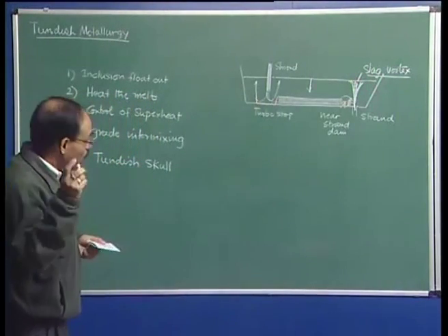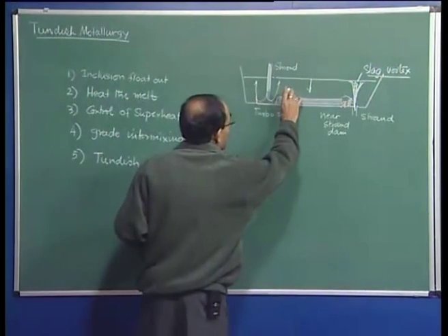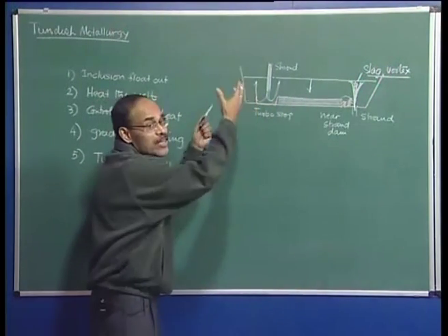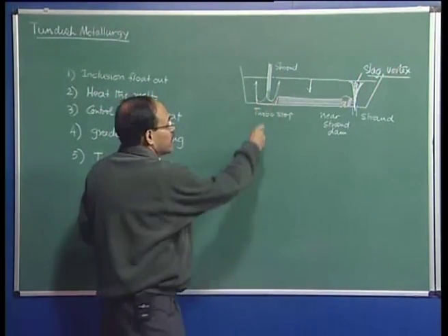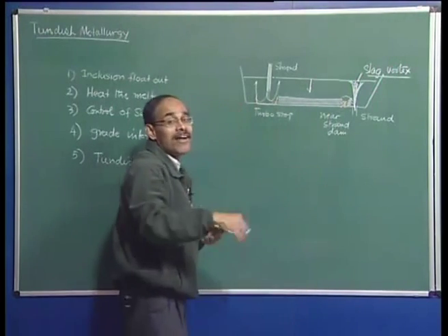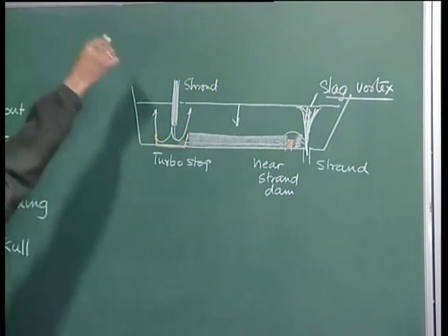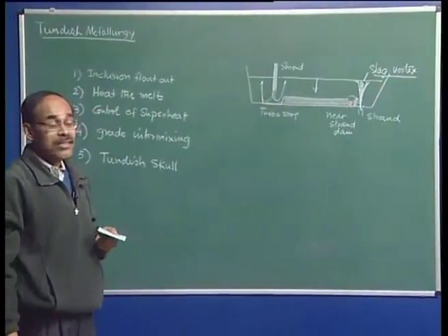And today we would like the residual volume of liquid, or the skull, because when this tundish is taken away for relining, this material will solidify and manifest as scrap or skull, and this skull is going to be recycled back into the basic oxygen furnace for production of steel.